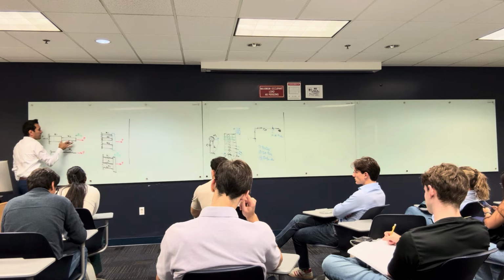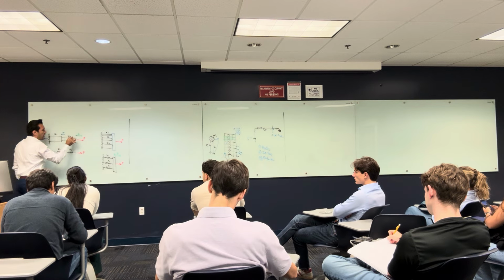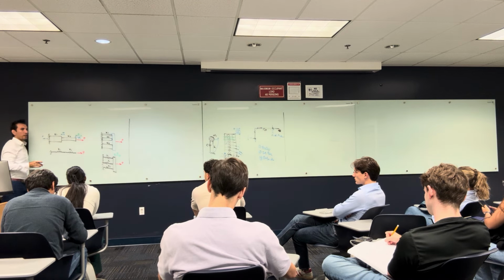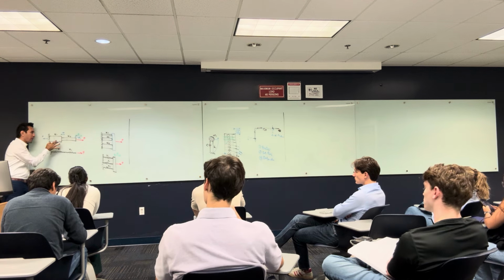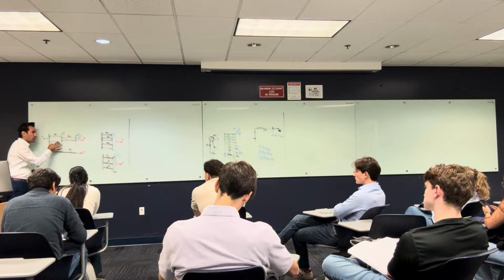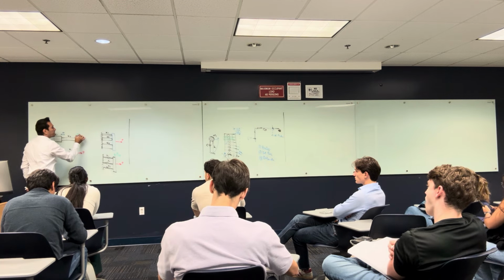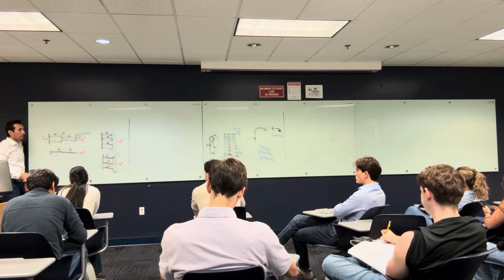But the thing is, this is less stiff than this. So I would imagine that this is going to have delta 1, and this is going to have delta 2. Which one is going to have more delta? The less stiff, right? You have to overcome this first, which is the most stiff one. And it's going to have delta 1, and the final delta is going to be delta 1 plus delta 2, right?